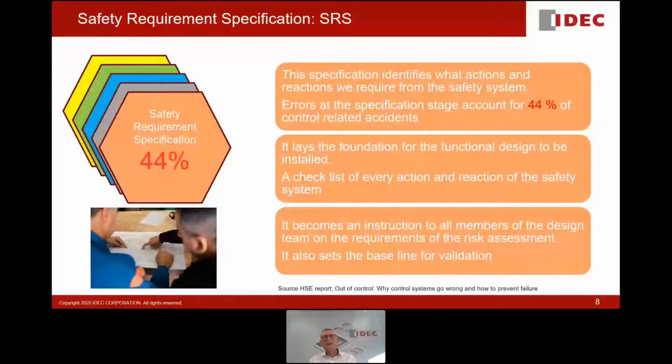And it creates a checklist of every action and reaction of the safety system. It becomes an instruction to all of the members of the design team. And if you have studied functional safety at all, you will see that there is a requirement for review, check, and review all the way through the life cycle of a piece of equipment.